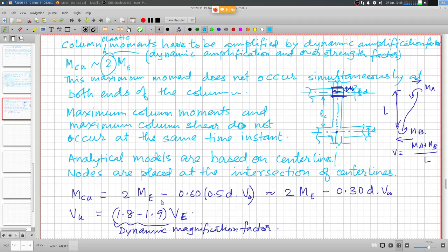The concrete should facilitate compaction, so we do not allow very heavy crowding of reinforcement, which will hinder the flow of concrete around the reinforcement bars.